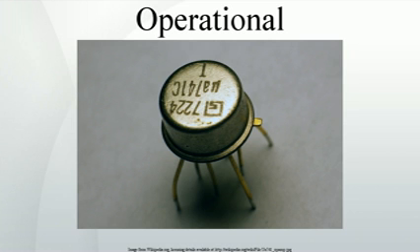A DC blocking capacitor may be inserted in series with the input resistor when a frequency response down to DC is not needed and any DC voltage on the inputs is unwanted. That is, the capacitive component of the input's impedance inserts a DC zero and a low-frequency pole that gives the circuit a bandpass or high-pass characteristic. The potentials at the operational amplifier inputs remain virtually constant, near ground, in the inverting configuration. The constant operating potential typically results in distortion levels that are lower than those attainable with a non-inverting topology.